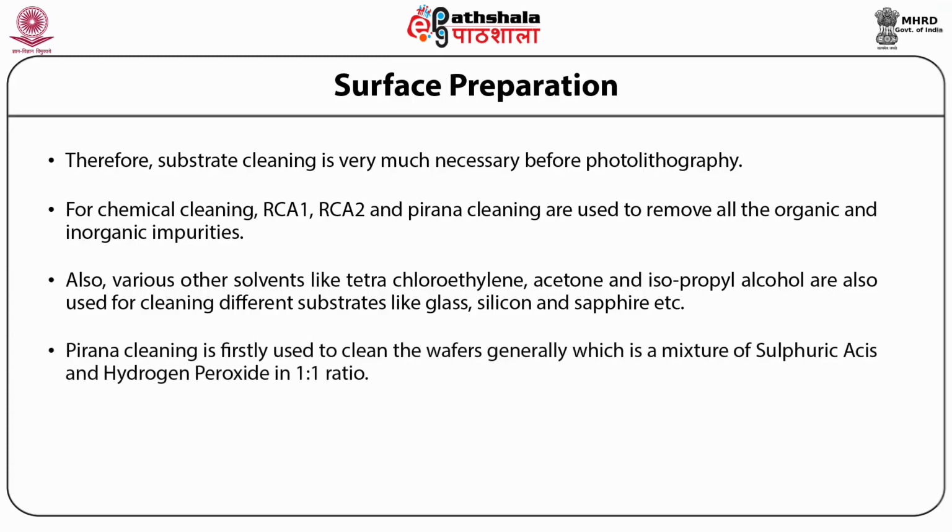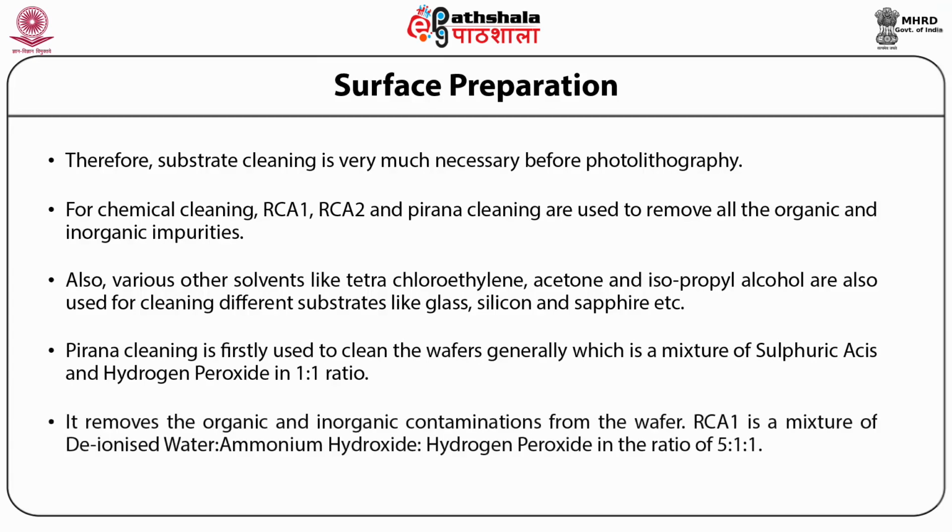Piranha cleaning is first used to clean the wafers generally, which is a mixture of sulfuric acid and hydrogen peroxide in 1:1 ratio. It removes the organic and inorganic contaminations from the wafer. RCA1 is a mixture of deionized water, ammonium hydroxide and hydrogen peroxide in the ratio of 5:1:1.